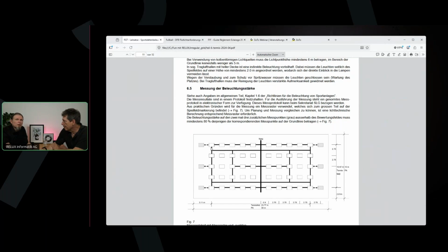And this grid, also this French grid, looks quite regular, quite even, like a normal grid. But the normal grids we use in ReluxDesktop and in all other lighting calculation applications are based on one formula, from Professor Stockmar out of Germany. It has a logarithmic part for calculating the distance between the calculation points.